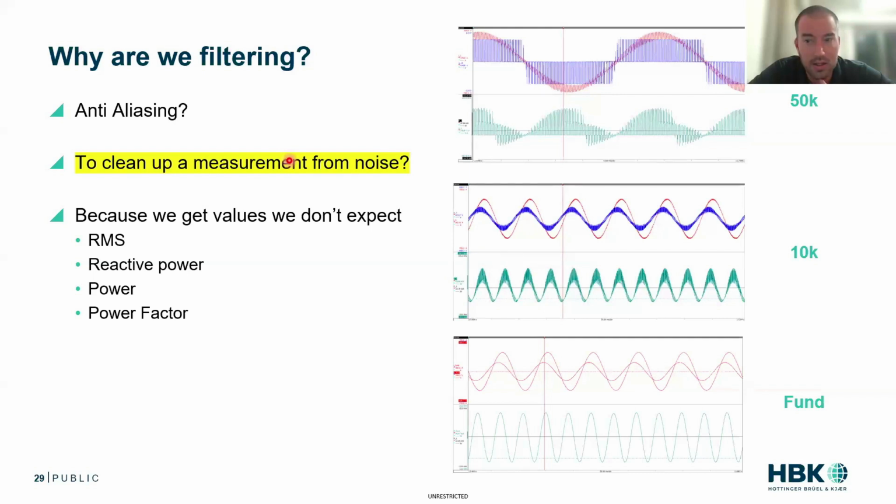And the scary thing is if you filter down to get an RMS value you want, you might eliminate some power. So think about, what's the bandwidth I need for power? What's the bandwidth my engineers want to see for things like RMS? These are questions they might have answers to, because it's things people don't think about, especially when they live in MATLAB and they say, put a filter somewhere, and they never think about it. You've got to ask yourself, what are the bandwidths we want for our different calculations?